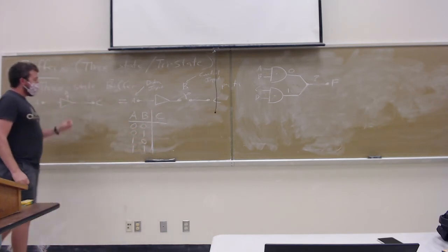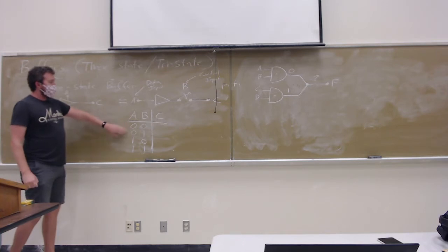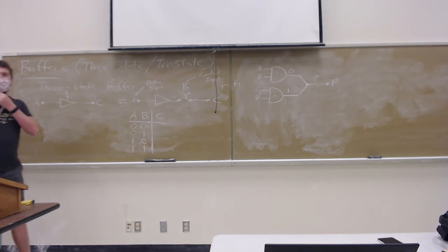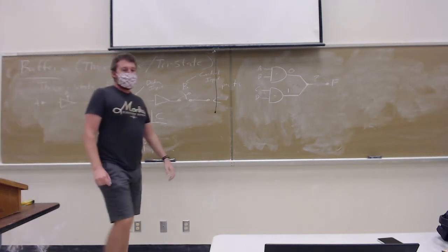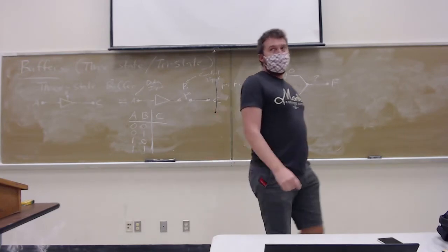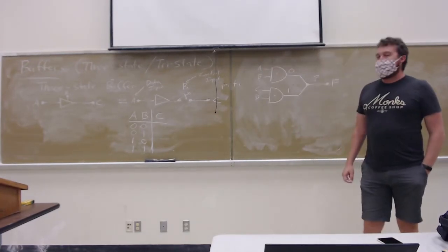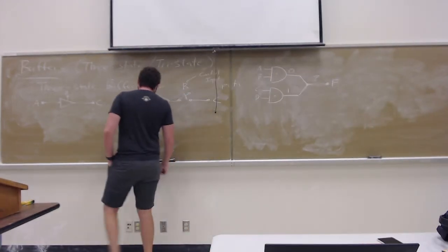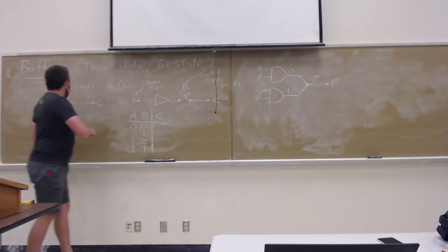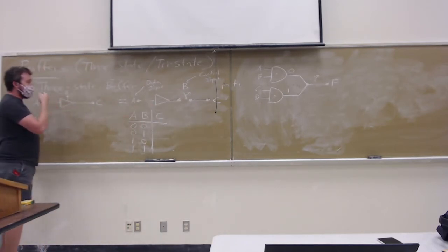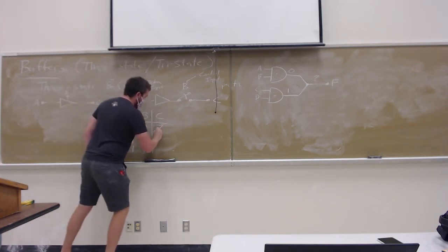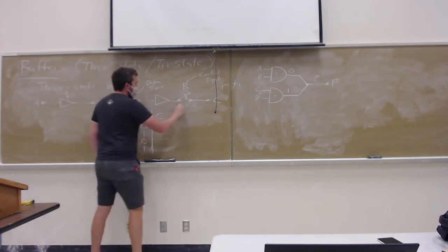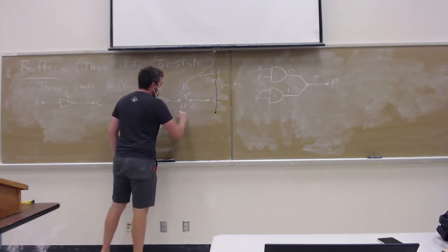All right, so let's fill out our truth table. We've got A and B on the left-hand side. First row, A is 0, B is 0. What will C equal to? 0. That's a good guess. All right, you're sort of right to think that it's 0, but it's not. In fact, we have to introduce a new symbol. The case when B, or what we call the enable for the three-state buffer, is equal to 0, we're going to denote with a Z. We refer to the state as high Z or high impedance.